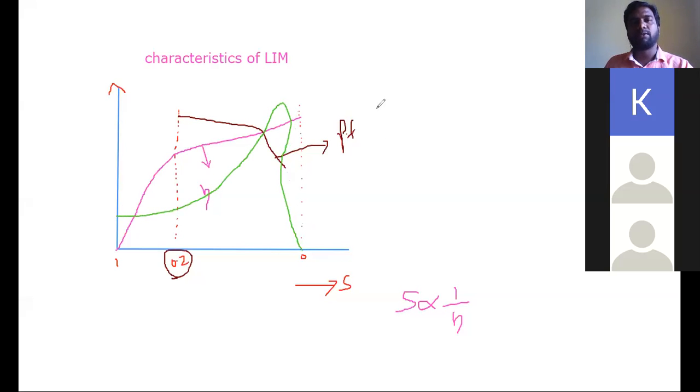So this is the plot for thrust force. If you see here, what happens when slip is 0? What happens to the value of thrust force? The thrust force value is also 0. When the slip value is slightly increasing, the thrust force value is maximum. If the slip value goes on increasing to 1, the maximum value for slip here, the thrust force value is reduced.